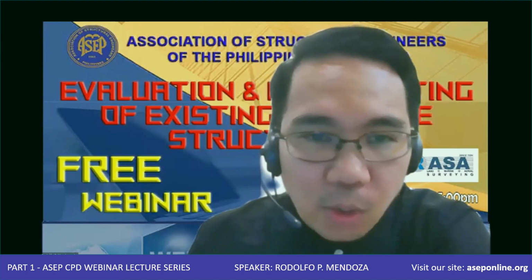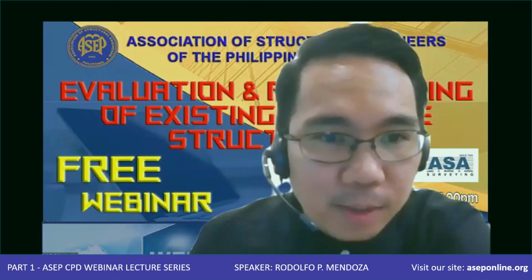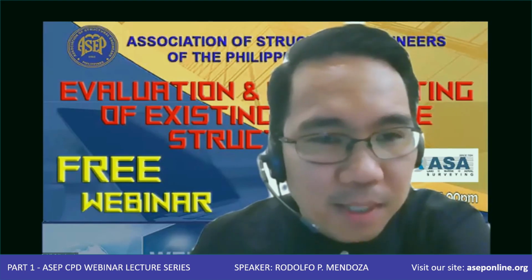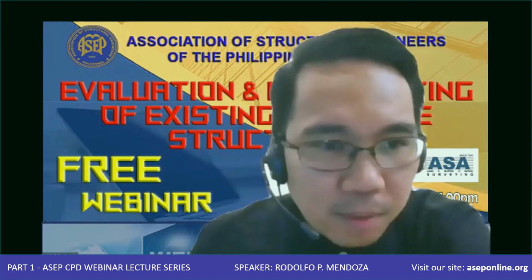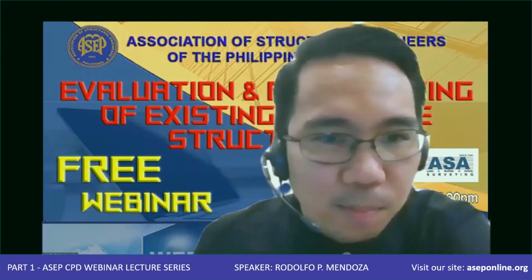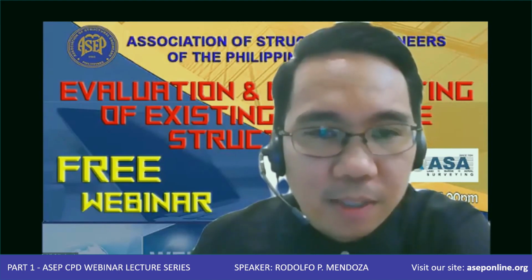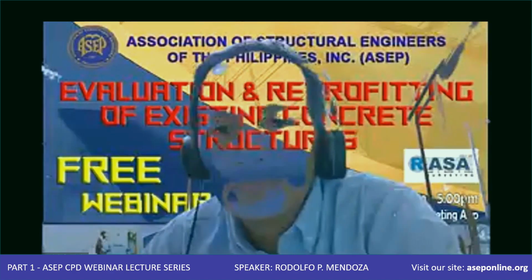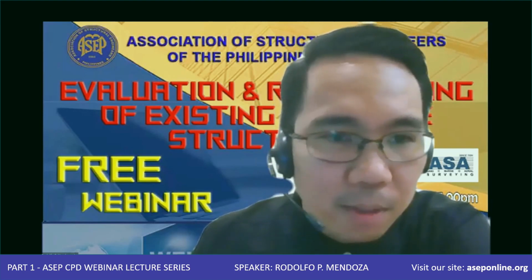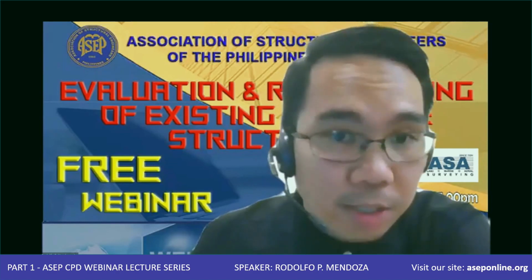Yeah, I think in doing an evaluation of existing structure, the first objective is to do a gravity assessment, right? Because the gravity assessment must be the minimum level of safety that you can provide. So if it can no longer support gravity loads, then you don't even need to conduct a seismic evaluation, because the first thing you should check is that the building must be able to carry the gravity loads that it supports, so that it can continue its service.